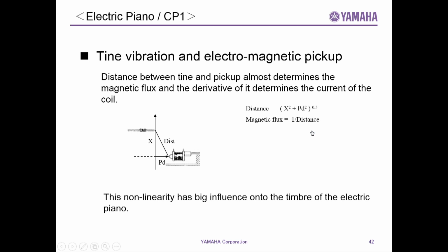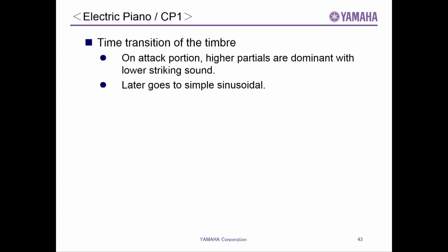how tine vibration can generate the voltage of the magnetic pickup is a very difficult issue, because when thinking about this kind of relationship between the tine vibration and the magnetic pickup electricity, they have a big nonlinearity. So the nonlinearity has a big influence on the timbre of the electric piano. We have to emulate that.